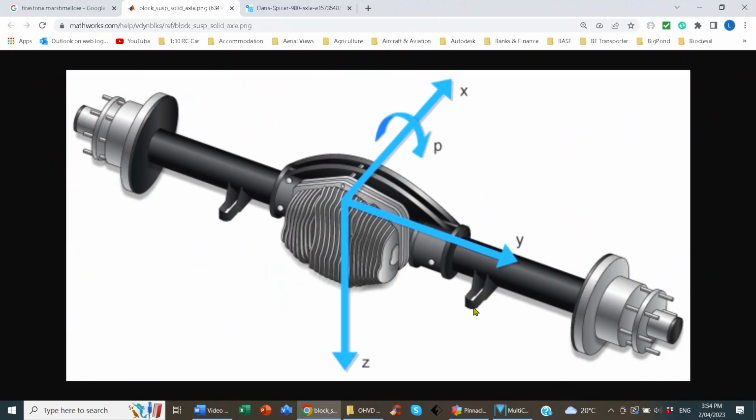Next, I want to do the same for axle types. And you'll note that it's sometimes difficult to differentiate between the two because they're so integrated. Alright, here's a very simple live axle: differential, tubes, brakes and hubs. So live axle, not independent. The pros for it: it's simple, it's easy, it's low maintenance. The bad is maybe a worse ride on light vehicles, and in things like fighting vehicles it requires a higher floor because the diff has got to be at the height of the axle. It can't be lower than the center of the wheels.